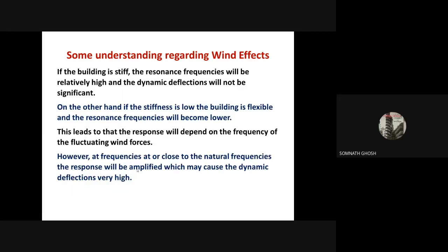You see, if the building is stiff, the resonance frequency will be relatively high, and the dynamic displacement will not be significant. That you all know, because you have probably taken a course on dynamics. On the other hand, if the stiffness is low, the building is flexible, and the resonance frequency will become lower. This leads to the response depending on the frequency of fluctuating wind forces.